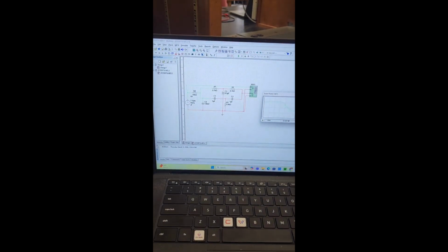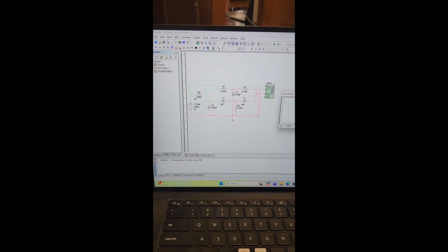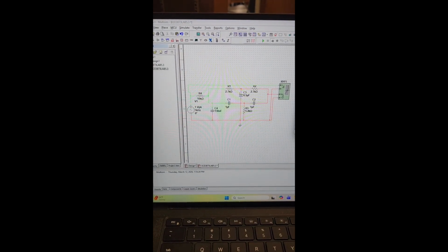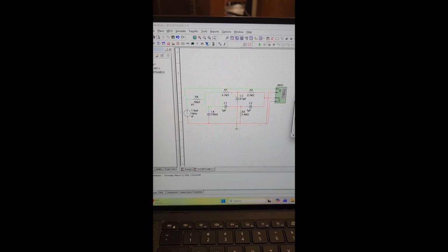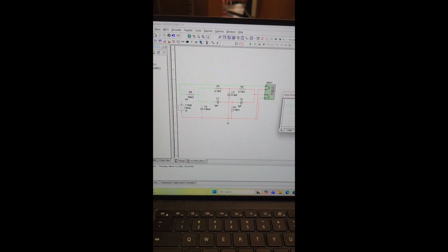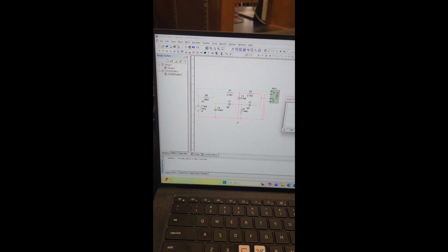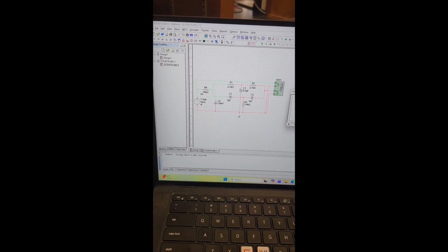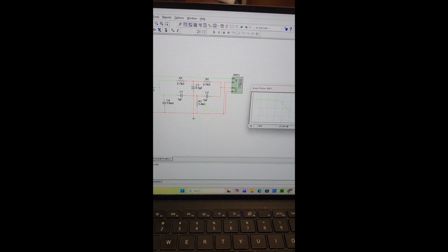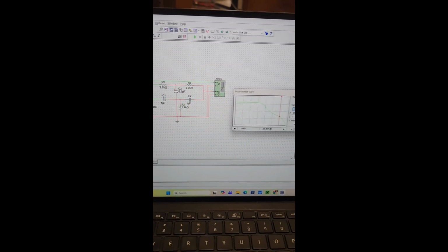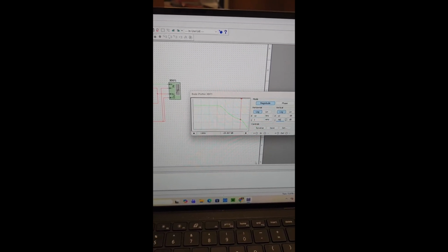Hello, this is Braden Black, and this is the second part of Lab 5, and this is the low-pass filter and notch filter combined. This is our Multisim, where we have the low-pass filter of the 10 kilo ohm and the 130 nanofarad. And that is our low-pass filter designed to have a cutoff frequency of approximately 120 hertz. And then we have our notch filter, and this is the combined result in the Multisim.